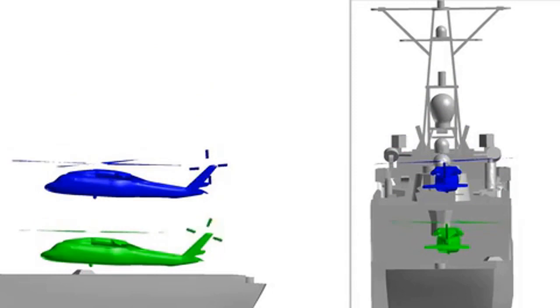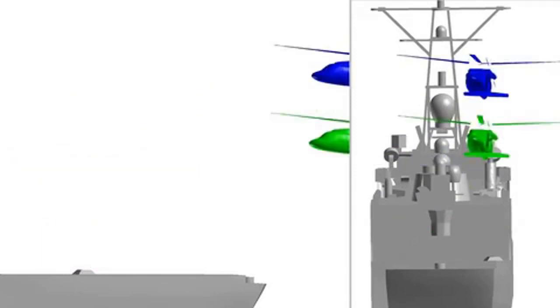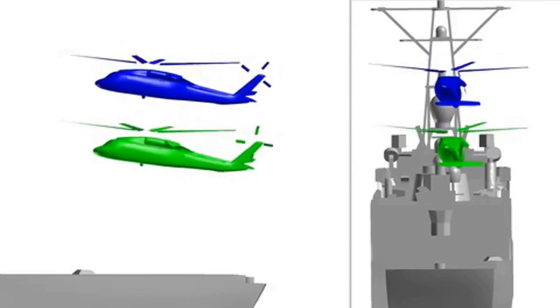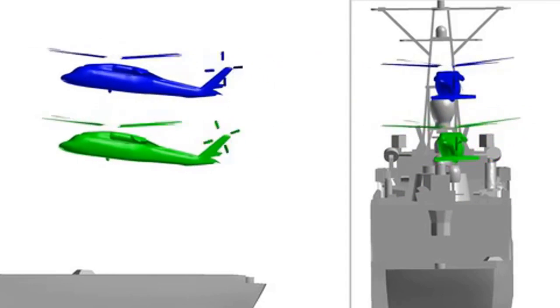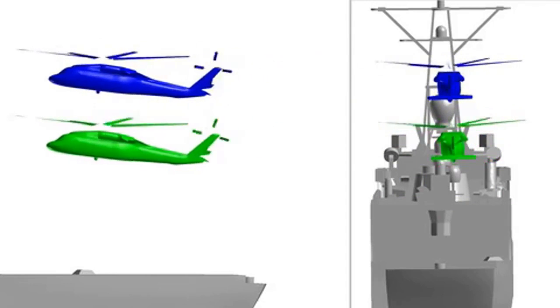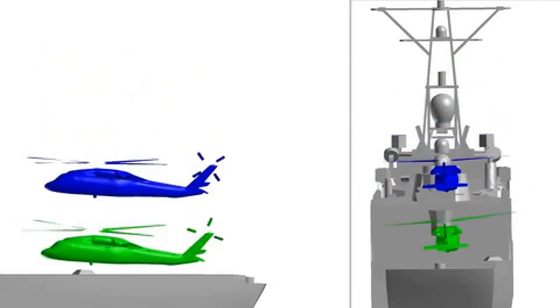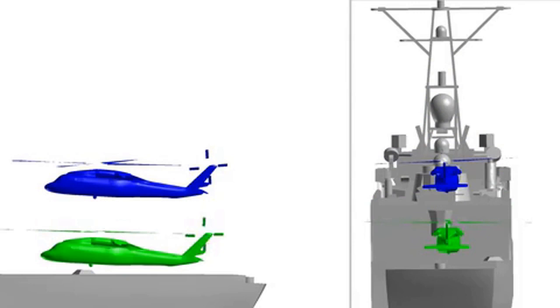And you can actually see the flight simulator has a landing gear model. So what you can see when it comes in and lands, that landing gear model shows it's landing on one wheel, then settling down on the other one. And I forgot to mention that besides controlling the rotors, the flight simulator is also doing the 6-DOF integration and giving us the Euler angles and positions of the aircraft in time that we're setting in the CFD.